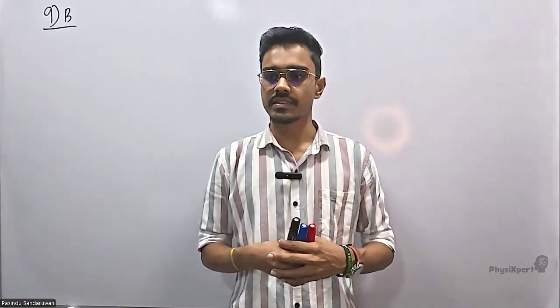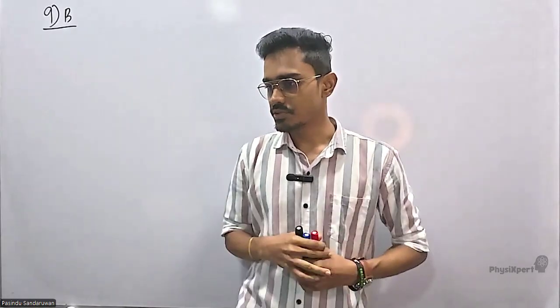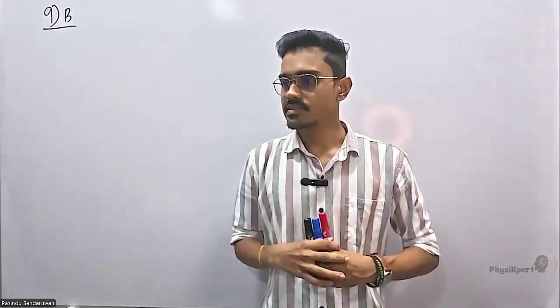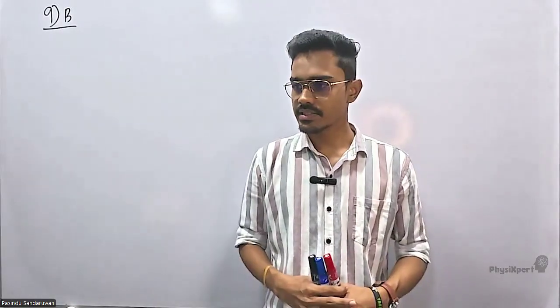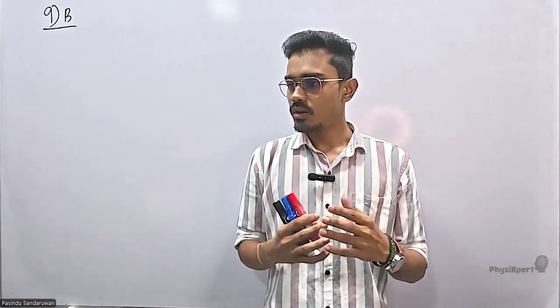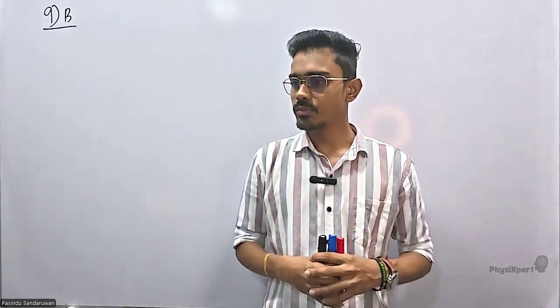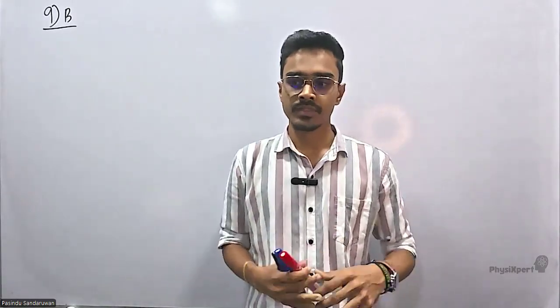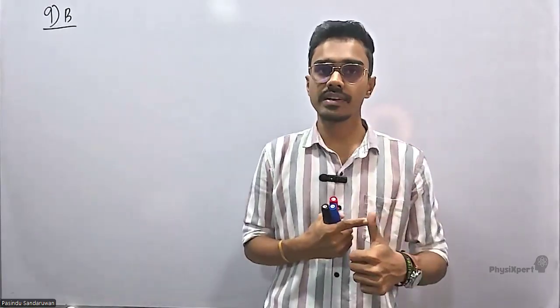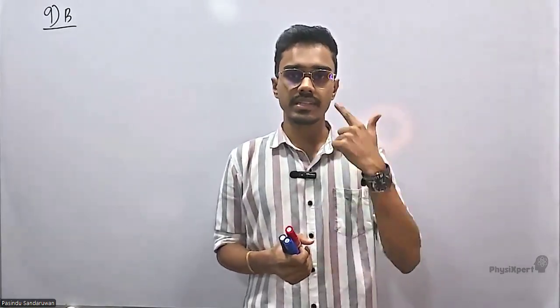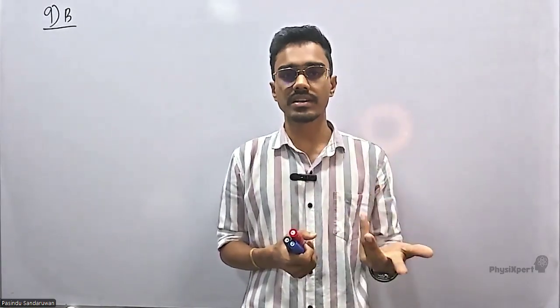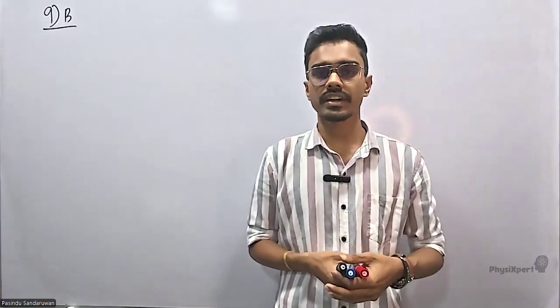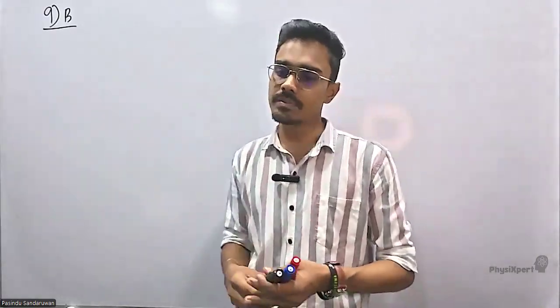All right. Question 9b, electronics. First one: why are field effect transistors (FETs) called unipolar devices? What are the charge carriers contributing to the operation of FETs? The reason to say unipolar devices is that only one type of carrier is contributing. In bipolar transistors, both types of carriers are contributing. So here only one type is contributing.